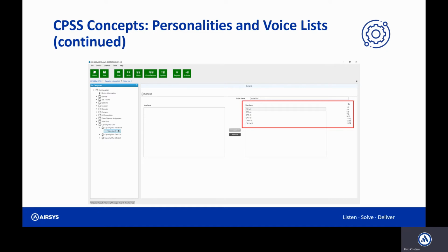And this is important because in a Capacity Plus trunking system, because there's no central intelligence, you need to tell the system in which order the repeaters are located in the system. And we'll look at this as well in the repeater programming. But every repeater needs to be given a slot ID. So the first repeater in the system will be allocated with slot IDs 1 and 2. The second repeater with slot IDs 3 and 4, then 5 and 6, 7 and 8, and so on.